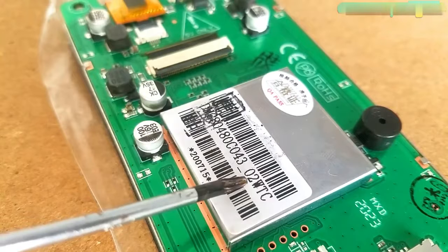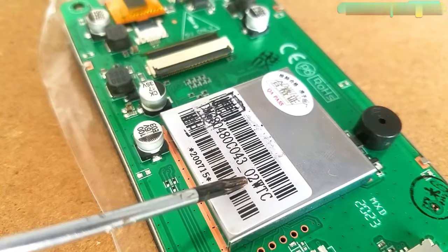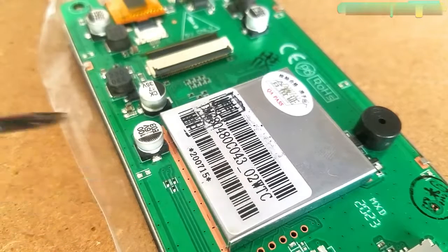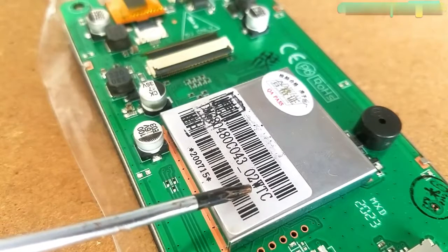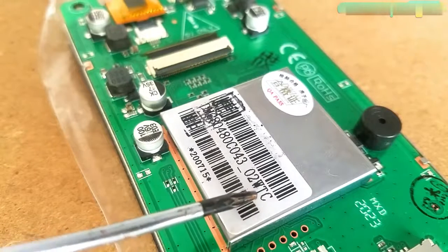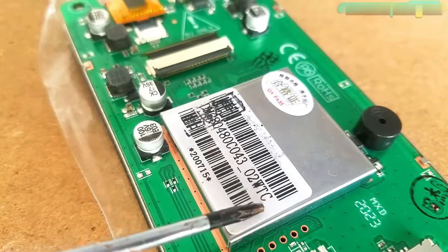This 1 digit represents the ROM ID, and it can be any digit from 0 to 9 to distinguish between different hardware versions. This 1 character represents the LCD temperature grade. For this LCD, W means wide temperature. The final 1 or 2 characters represent the TP category.